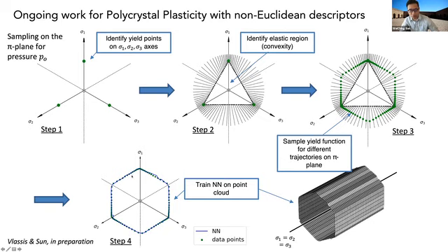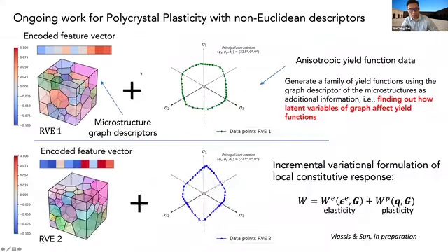What is the shape of the yield surface? And I'm surprised that we find something very close to the Tresca yield function for the polycrystal structure, and we still want to know why. But this is the general result. So as you can see, this is anisotropic. So when we rotate the crystal orientation, we get a different yield stress.